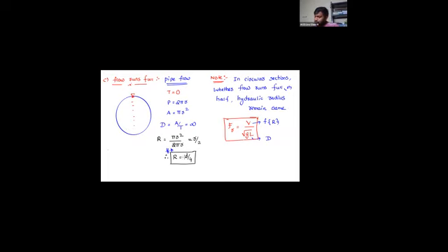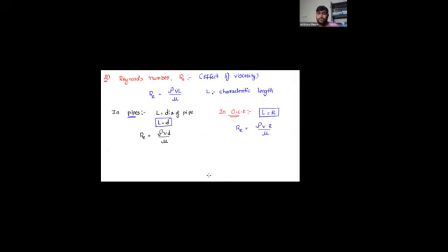So I told you whether the flow runs full or half. What is the meaning of when flow runs full? The meaning of flow runs full is pipes. In the case of pipes, R is equal to D by 4. Yes or no? Now can I substitute D as 4 times R? Then I can rewrite this, D can be written as 4 times R. So now rho V into 4R by mu. You can see the Reynolds number in pipes is different. The Reynolds number in open channel flow is different.